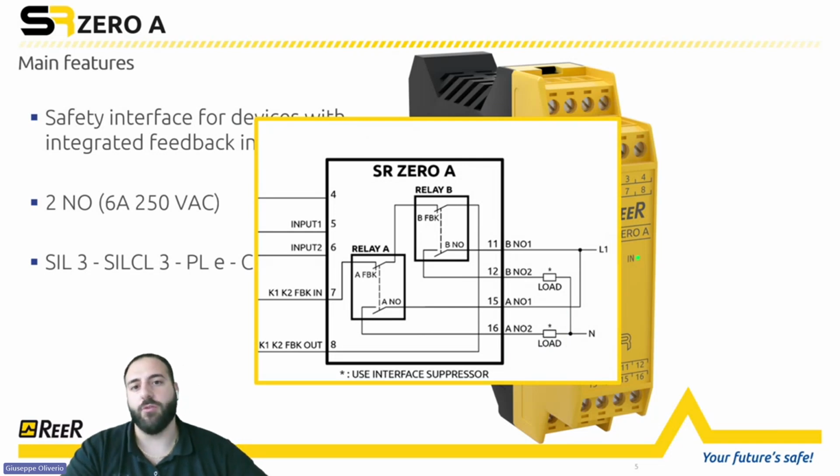This depends on whether you need another signal, a normally closed signal or not, because you also have to consider the electrical diagram that we have inside the interface module. So if you need one more normally closed contact, then you can go with the SR0. If you just need to connect the normally open contacts to drive the actuator or to go into external contacts, then you can go with the SR0A.